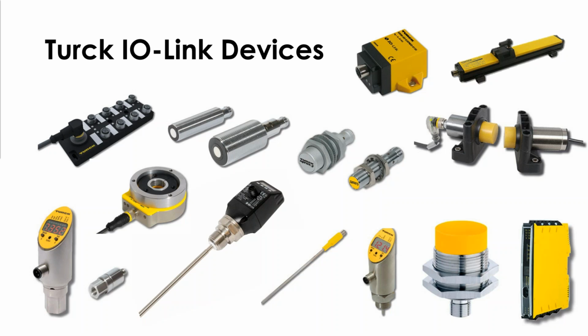Thank you so much. Okay, so the encoder here, it's a 0 to 360 absolute device, and if it's powered, it will also keep track of turns. So as long as you're not moving when your power's removed, you could use this as a multi-turn absolute device over IO-Link. Then we also get into the RFID readers that I mentioned, linear position devices, ultrasonics, several different things.